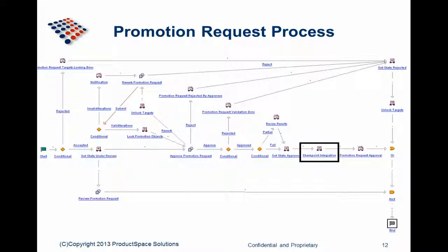Next step in the process is to design the triggering point in the source system. Here in this case, promotion request workflow is updated to trigger the integration upon document release. Exception handling logic is also implemented here. Triggering integration through workflow is one of the possible approaches. We can also design listeners which work in the background to trigger integration upon certain events.